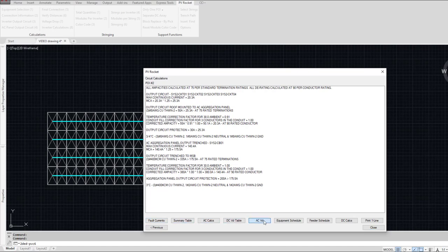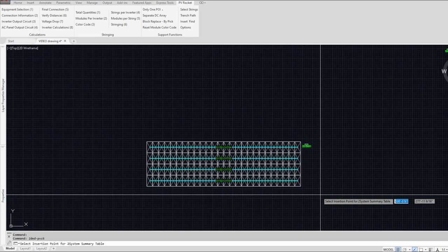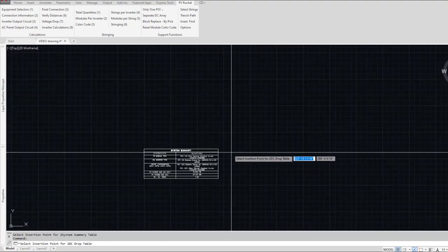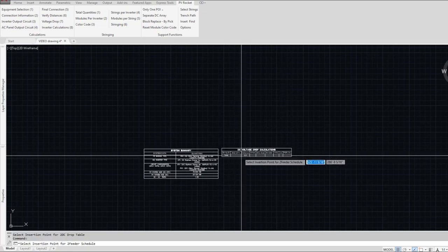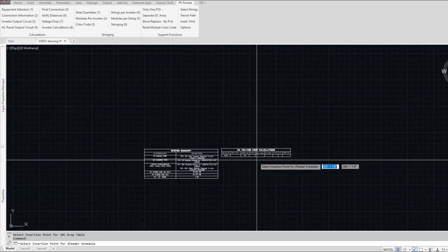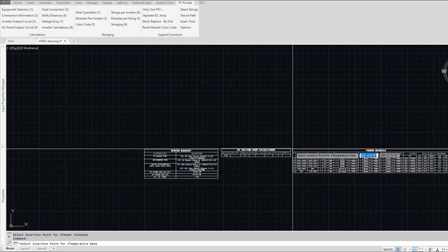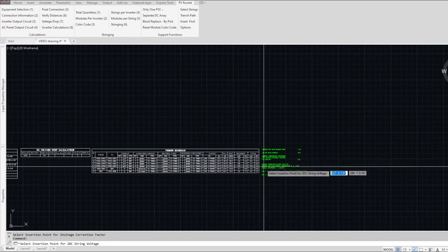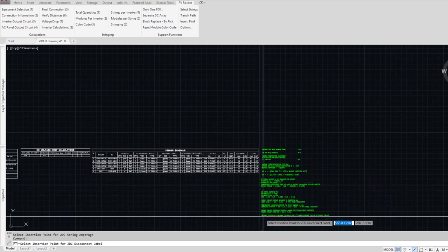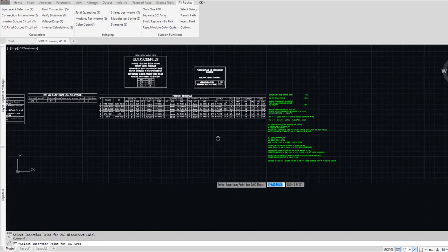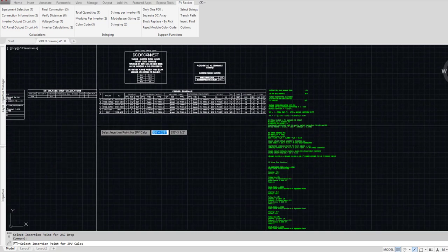I'm gonna go ahead and just get me some outputs for you to look at. We'll put them right here. Yeah, DC voltage drop calculation. Look at that. That box is nice and empty because it's a microinverter circuit, so it's going from right out of the module straight into an inverter that's 2 feet or a foot. Not going to happen. So it'll print out for you.